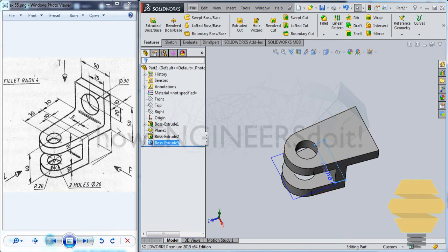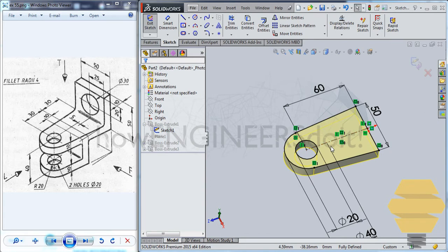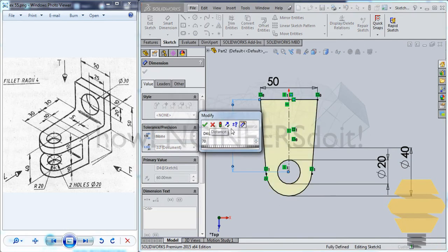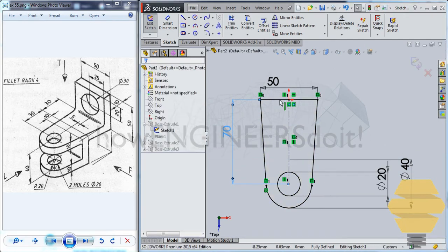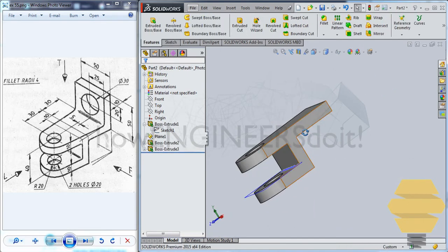So as we see here, if I just go for the first extrude to the sketch, Ctrl 8, you'll be able to see that I have taken the dimension from here to here, but you can see that there's a thickness for this, right? So let's also add that thickness there. So that should be a 10 extra, right? So I'll give 70, enter, tick mark, exit sketch, and you can see that it's already reflected there.